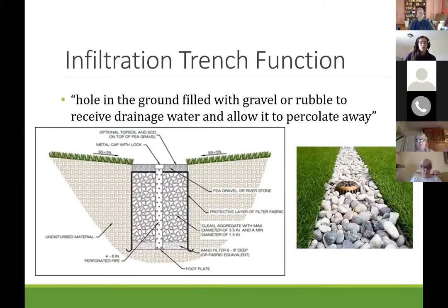These two things work the same way. So we're just going to go through and give an example of what a larger size system, the infiltration trench, is. Basically, the infiltration trenches are just holes in the ground, which we fill with rock material. Dry wells, there are some do-it-yourself kits that you might see at your local hardware store that look like a trash can system. It's empty in the middle, so that gives more void space. So you can take more stormwater if you just have a hole that's empty as opposed to the gravel system.